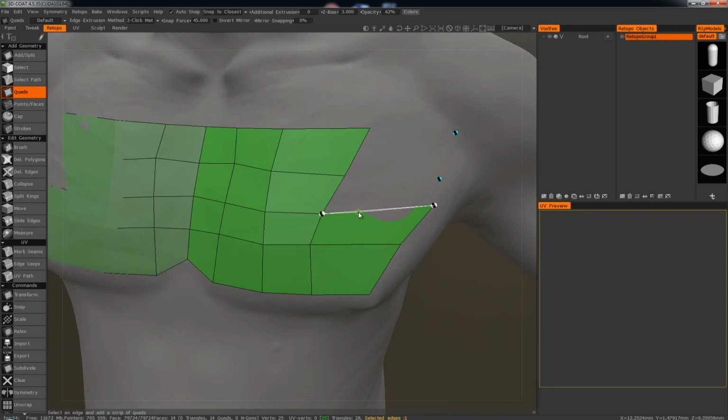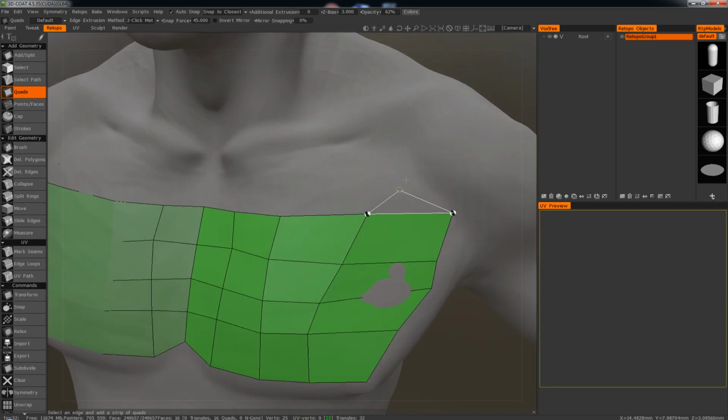Once you select it, it's going to allow you to select this vertex and then snap with this one. And now you have this done. So again, this one and this one. This can also be used to manually add in vertices like this. So you select one edge, add in two vertices, two more, and quickly build up the mesh.